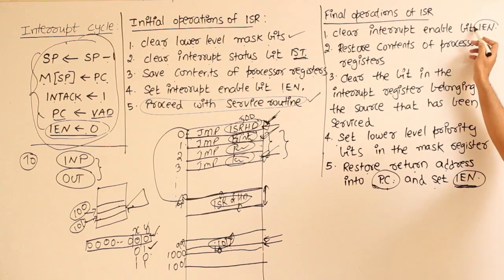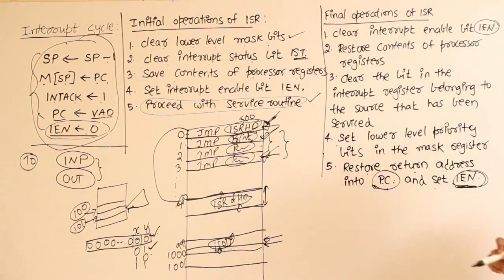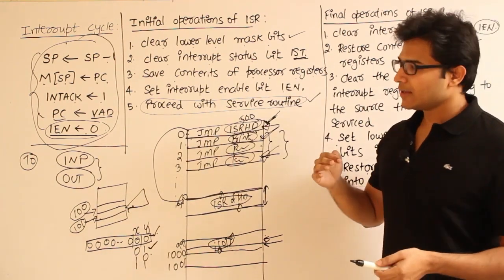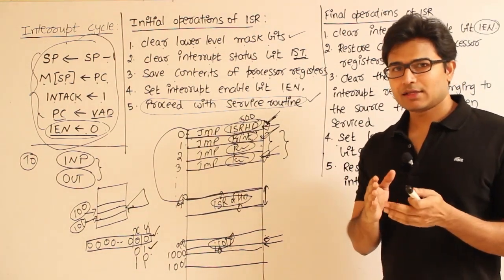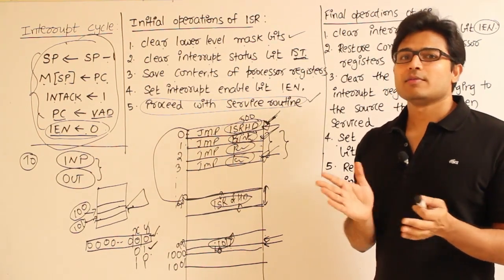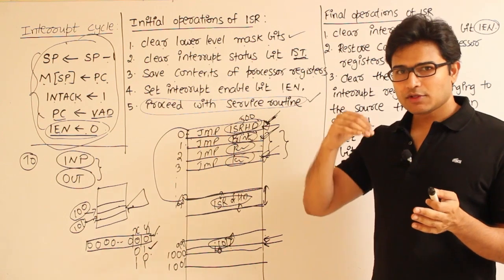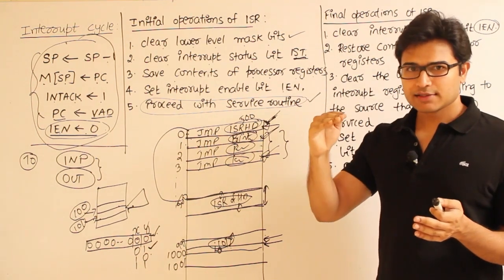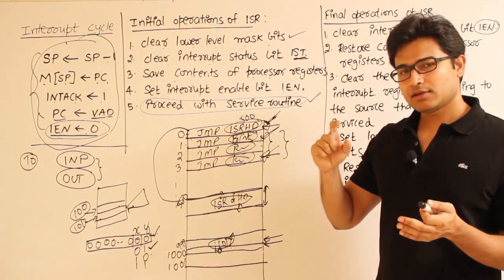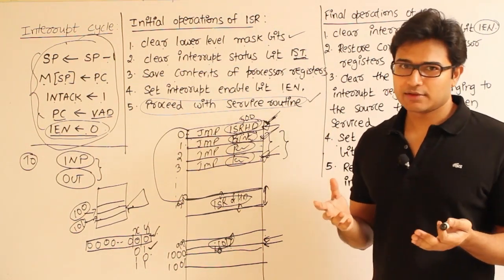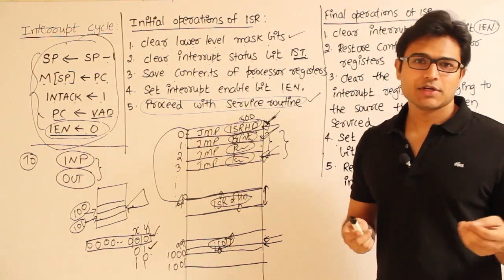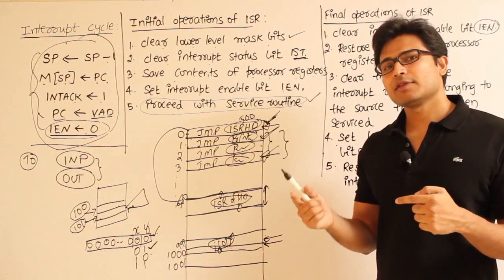So here you have cleared IEN. Now again you are setting it back, right? See this. There are certain tasks during which we should never be interrupted, which means when we start performing those tasks, no one in the middle should disturb you. That is generally called atomicity, right? Atomic units. So during that part, we are disabling the interrupts and again enabling the interrupts once that is